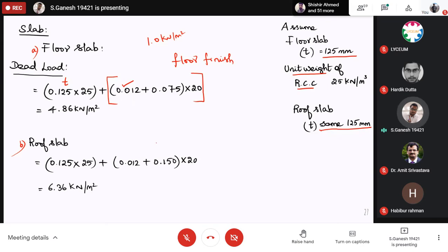In a detailed calculation, if you want to know it in a very perfect manner, suppose some client is using tiles or marbles or flooring tiles whose thickness is heavy, according to that we can adjust the size over here. We generally take 12 mm and 75 mm as the floor finishing thickness, multiplying with the cement mortar.